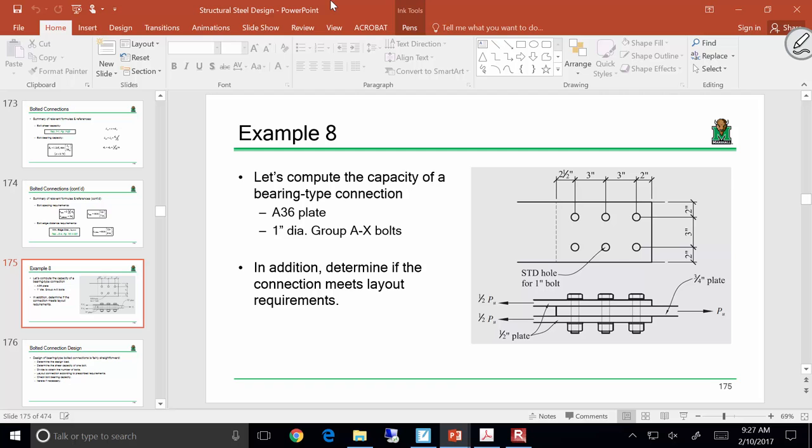When we do bolt bearing calcs, we always have to look at at least two different situations. What are you doing in a connection? You're taking member A and connecting it to member B. When we're doing bolt bearing calculations, we are evaluating not the bolts, we are evaluating members. So theoretically, we have to do at least two bolt bearing checks: one for, in this case, plates transferring load to the left, and another for plates transferring load to the right. Make sense?